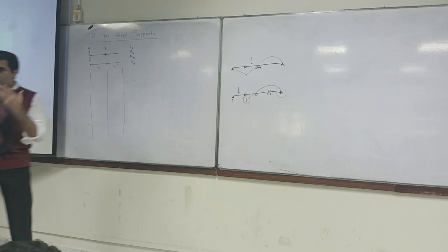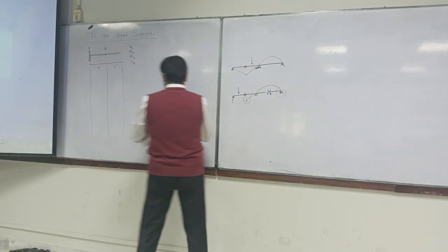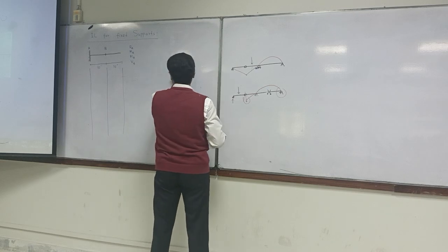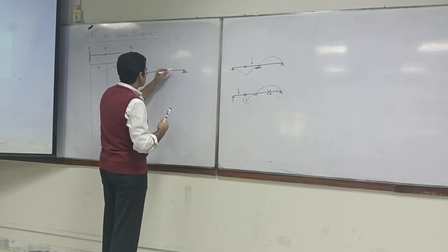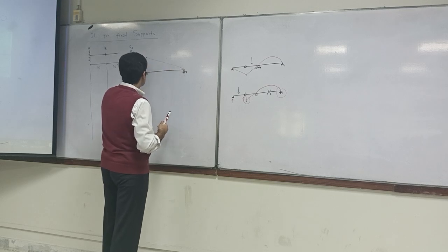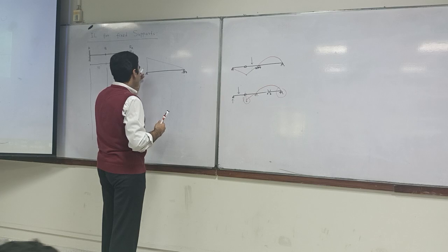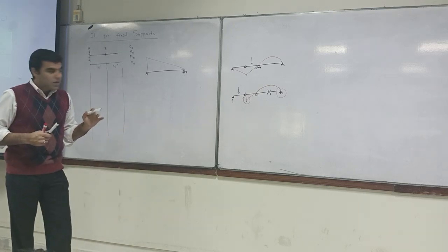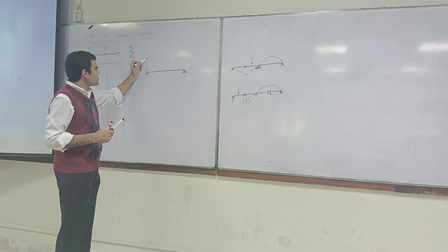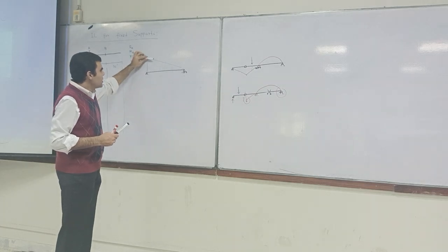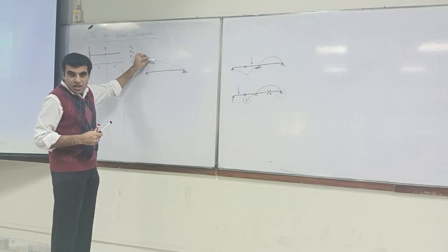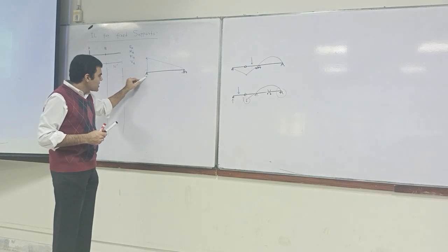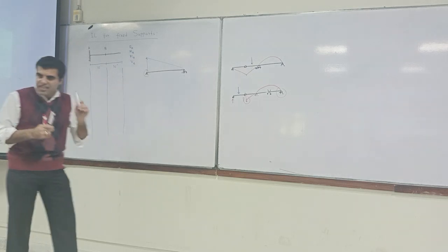Okay? In the case of pinned support, when we move our structure, so for example, if we had a pinned support, a simply supported beam, and if we moved it up, for example, in case of finding out reactions, it didn't matter whatever the inclination of this member was. Why? Because the kinematics of this pin connection allows any rotation.